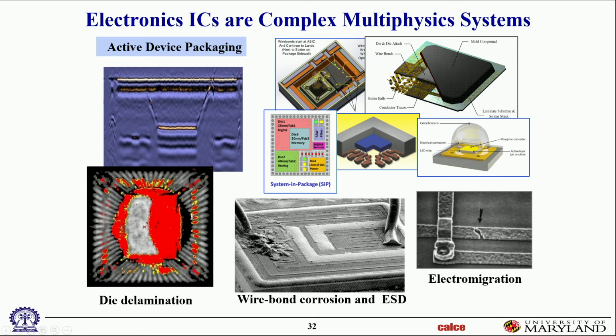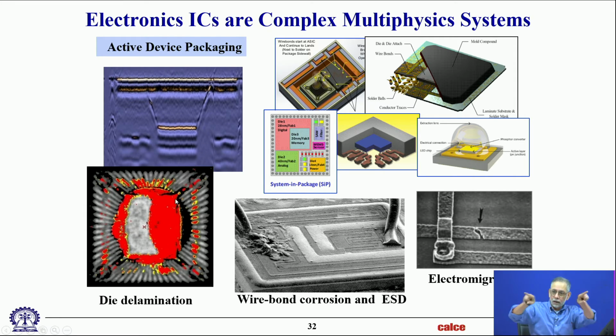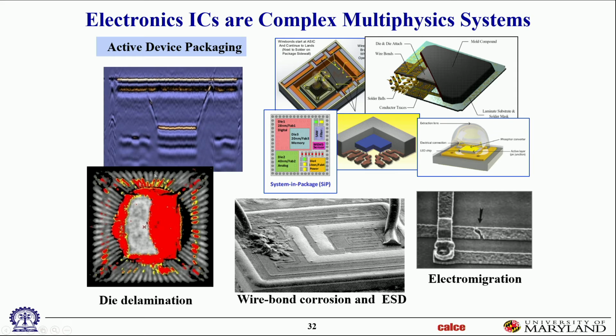These are delaminations that have happened. This is a C-scan, acoustic C-scan of delaminations of lead frames. So this package is a little bit different from that package. That package does not have a lead frame. This package is a little different. The die is on a central, and I'll show you pictures of all this later on, more details. The die sits on a metal frame. There are metal leads, metal fingers that come out on all sides, and now you can connect to the other end of those metal lead frames, and now you've got electrical connection into the die.